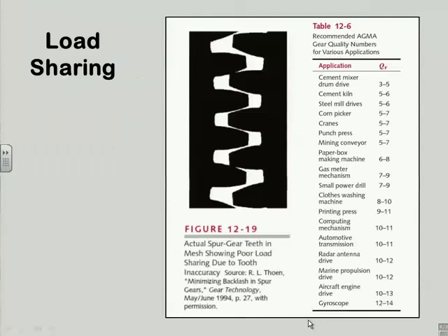This is what I was referring to by not well meshed gears. And this comes right down to how much money you want to spend. So if I want to spend cheap money for gears, I'll probably get a set that look like this. So this shows 2 actual gears in mesh, and they've got a big contact ratio because they're both very large in diameter compared to the tooth size. And notice that I can see the second pair down. Actually, it's the first pair because the top one isn't a pair.